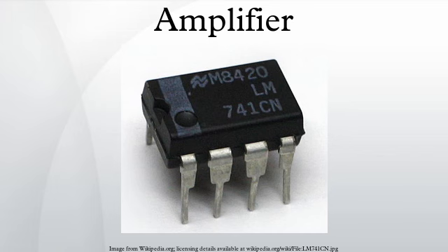An early use of Class D amplifiers was high-power subwoofer amplifiers in cars. Because subwoofers are generally limited to a bandwidth of no higher than 150 Hz, the switching speed for the amplifier does not have to be as high as for a full-range amplifier, allowing simpler designs. Class D amplifiers for driving subwoofers are relatively inexpensive in comparison to Class AB amplifiers.